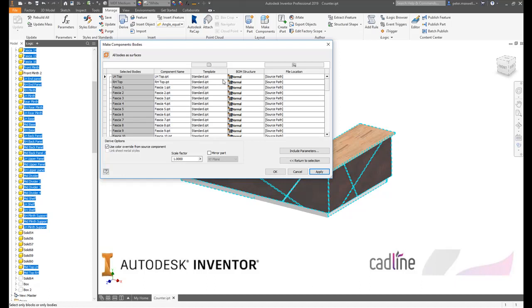However, because I'm using the sheet metal template, even though this is wood, I'm using a sheet metal template, this will automatically assign a material to that individual part. So I've got different thicknesses going on. The top is made out of 22mm ply, the rest of it is made out of 18mm MDF. So I'm going to choose 22mm ply nest template for the top pieces, and then go through all the other pieces and choose whichever template I want, basically. So these ones are all going to be 18mm MDF.